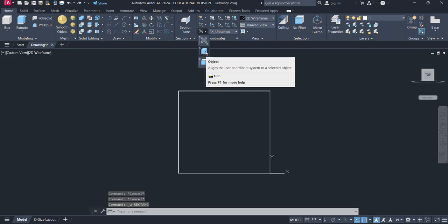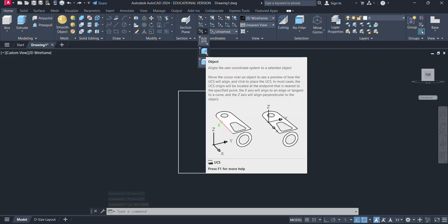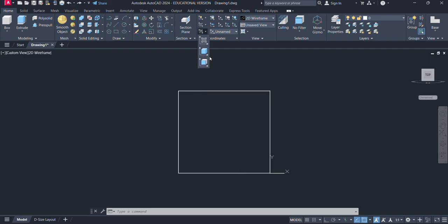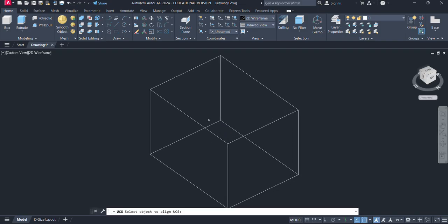The next option, as you can see here, is object. Now this only requires a plane. For example, I click in here, I can click on any plane. For example, this, as you can see here, the axis is changing. XY in this plane, see, XY has changed to a vertical plane, and again to a vertical plane, and it's horizontal again. So whichever line we click on, whatever the direction of that line is, it will switch to that plane.